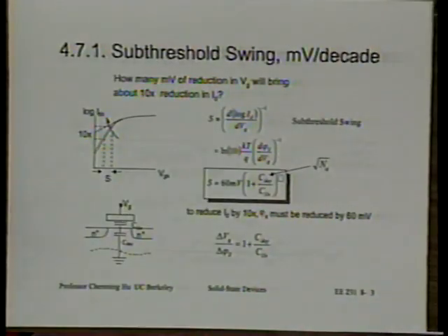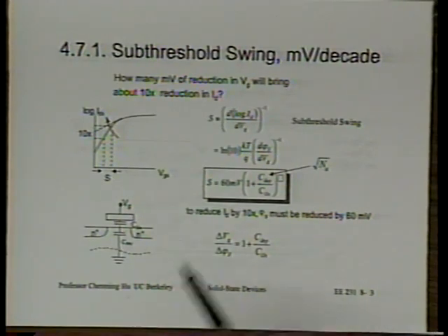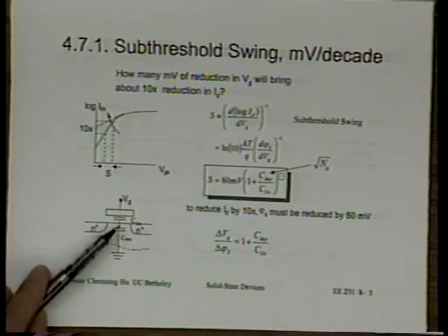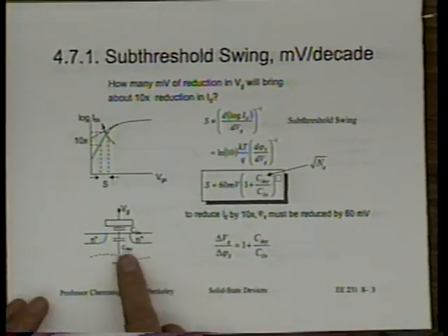We simply quickly go to a simple approximation. This approximation happens to be a very good approximation for retrograde doping again. That is, we just don't consider this depletion layer thickness to vary with any bias voltages, not even Vg. Let's assume there's a fixed WD max. In other words, the C depletion is fixed.